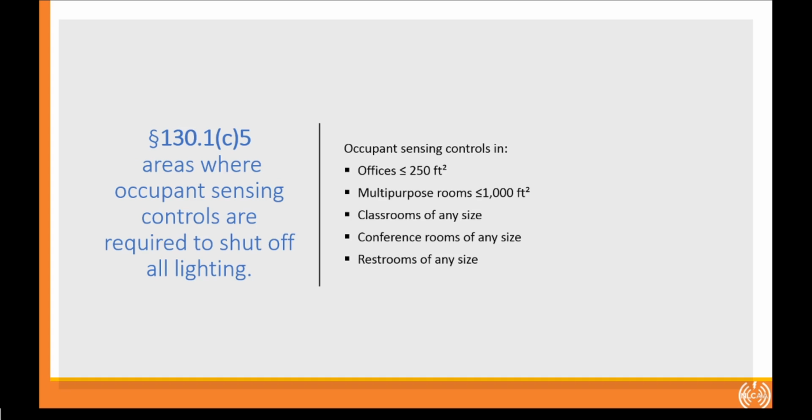So this requirement, whether you do vacancy mode or you do partial on mode, applies to all of these 5 spaces. Okay. Let me correct myself. Applies to 4 spaces. Restrooms don't have to follow this partial on or vacancy mode requirement. It could just be automatic on.